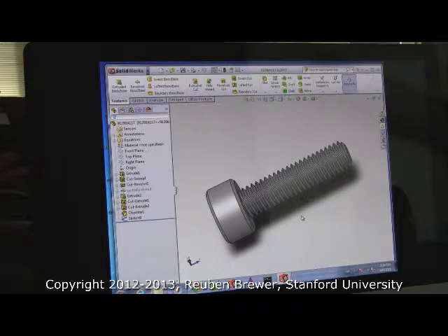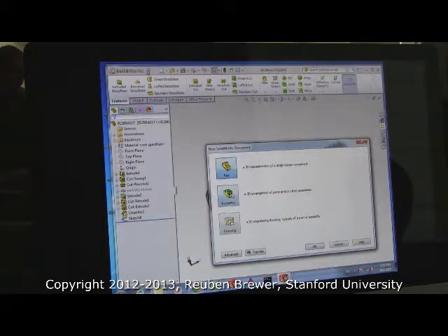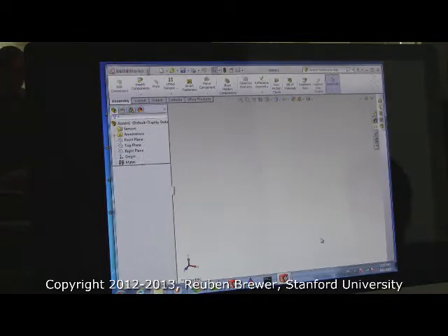I have had this be an error repeatedly at the machine shop where they screwed up, or I screwed up, and I had the wrong number of threads in my hole for the number of threads in my screw. This class, I want photorealism. You should be able to take a snapshot of your CAD and it looks like your robot. That's the only way robots work. I've had so many errors of I didn't include a screw in my CAD and the screw head, when I assembled it, knocked into something else. Not cool. So we have to put screws in, download them from McMaster. Okay, go ahead, File, New, Assembly. Okay, what's an assembly?